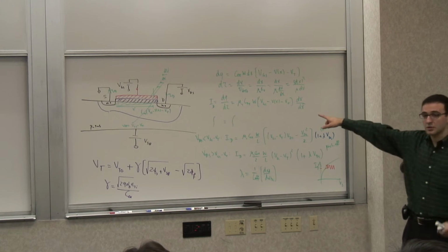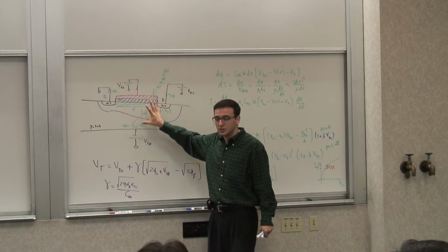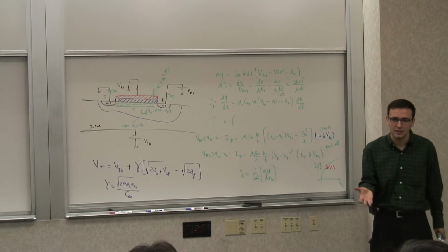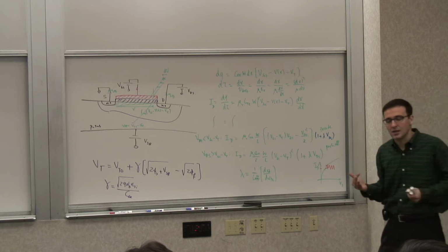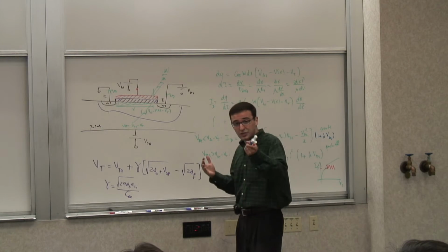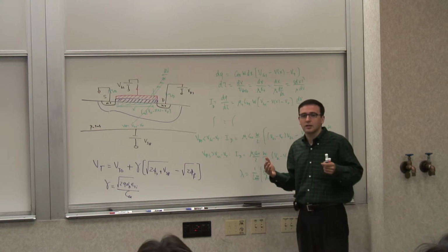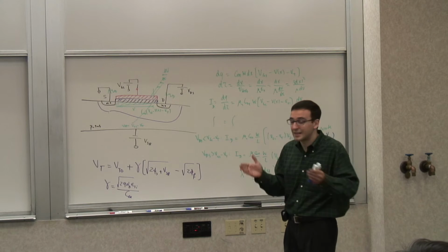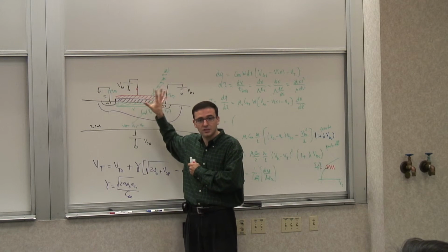But it doesn't solve the differential equations by the time. If you want to do that, there are different kinds of simulators. So the simulators we're talking about here are circuit simulators like SPICE, which are implemented in Cadence, ADS, different kinds of things. But there are device simulators that actually do what you just said. Like Pisces and Medici and all those device simulators, they actually go and look at the carrier equations and the differential equations and they solve those.